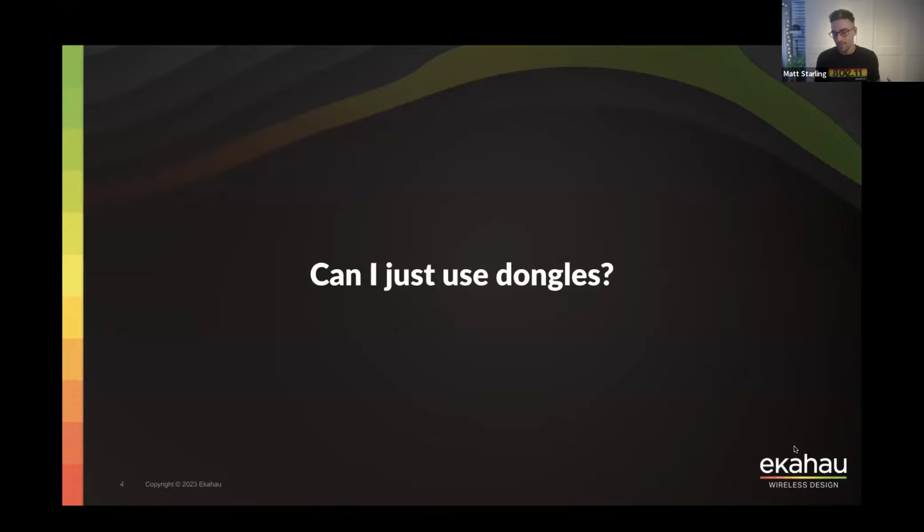And not only is it uncomfortable, impractical, not so mobile, the problem is that dongles are just so wildly inaccurate. If I was doing a validation survey with the same dongles as Mac, and he's walking right behind me, when you compare the survey results, my readings might say that I've got fantastic signal strength, minus 50 dB in that particular location.